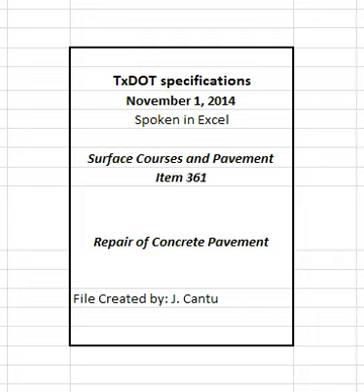Start at the center of the repair area. Ensure all loose concrete materials are removed and only sound concrete is left in place. Increase the repair area and perform a full-depth repair as directed if longitudinal steel bars were damaged by the removal operations. No additional compensation will be made. Clean the area to be repaired by approved methods. Remove all loose particles, dirt, deteriorated concrete, or other substances that would impair the bond of the repair material.